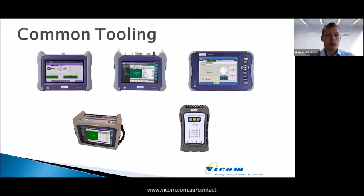Second of all, what sort of tests are you undertaking? So if you're in the utility industry, maybe C37.94. If you're just doing commissioning basic single service Ethernet links, maybe RFC 2544 and so on. And then in a lot of these tests, especially commissioning new Ethernet links, you're also going to require a loopback device. So do you want to get two of your identical units, one with a loopback option, or do you want to look at a dedicated loopback device, such as the network companion?